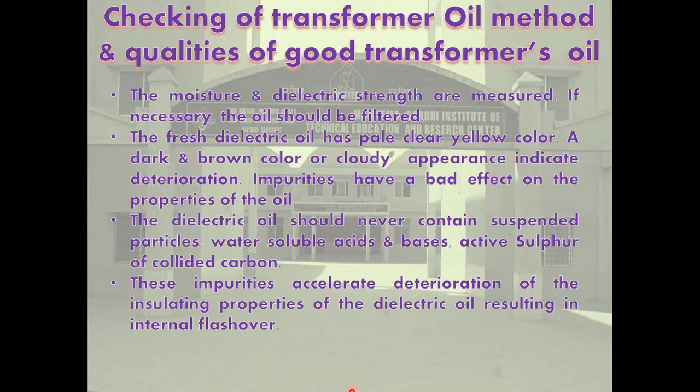The dust particles, carbon particles, and sludge suspended in oil gather along the conductor and insulated surfaces in presence of electrical field. Thereby, a thin conducting layer is formed gradually along the surface of internal insulation during service. The flashover can occur along the surface of the insulation or tank due to cracking.